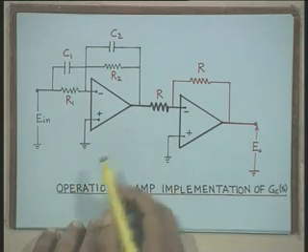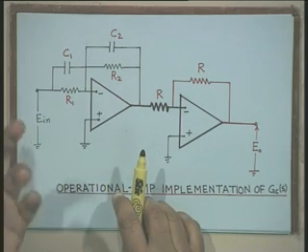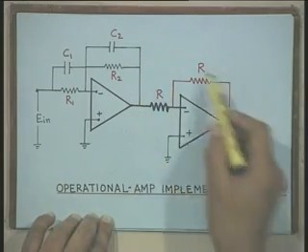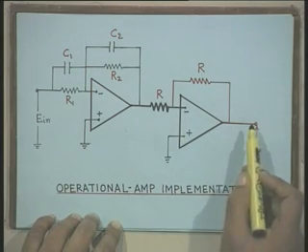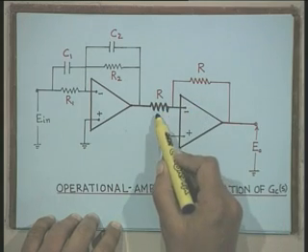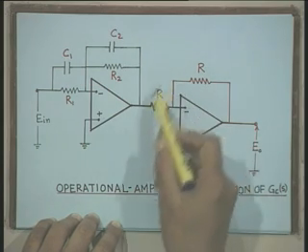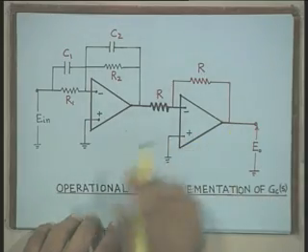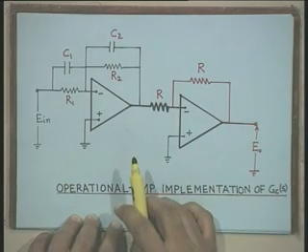Now, we all know that when you use one operational amplifier, there is a phase inversion. Therefore, to correct for this phase inversion, we make use of one more stage of operational amplifier, because in this particular case the gain is 1, or the feedback resistance is taken the same as the input resistance, so that the gain of this operational amplifier is 1 and the phase shift is 180 degrees. Therefore, the phase shift created by this operational amplifier is corrected by the second operational amplifier.